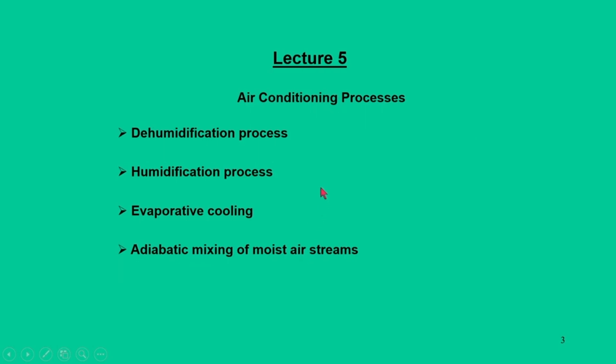If you think about air conditioning processes, there are 4 fundamental processes: dehumidification processes, humidification processes, evaporative cooling and adiabatic mixing of moist air streams.